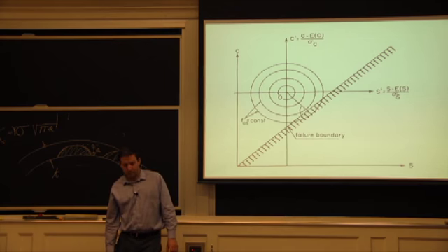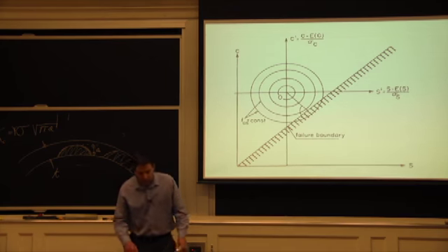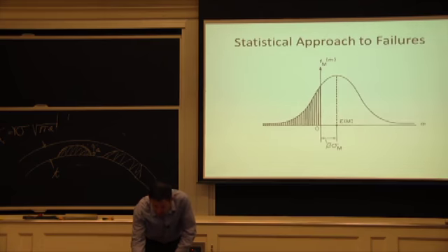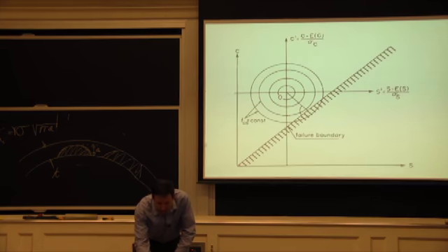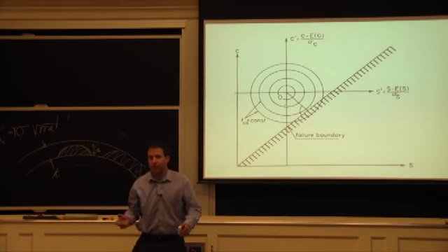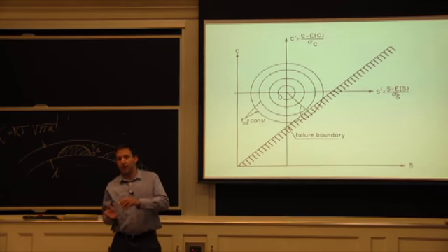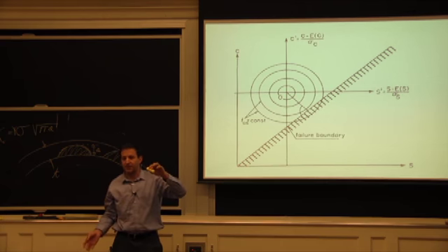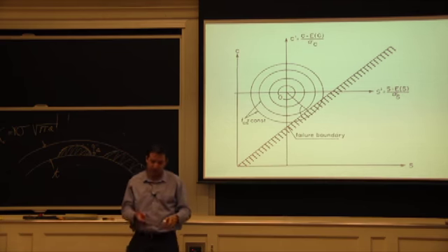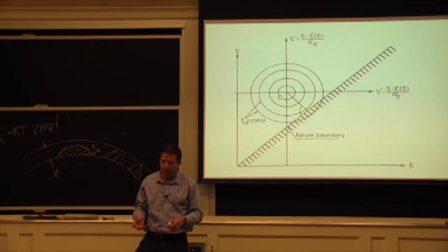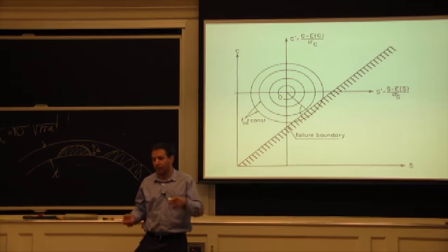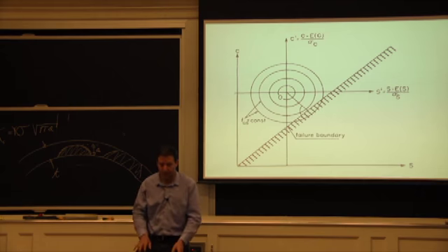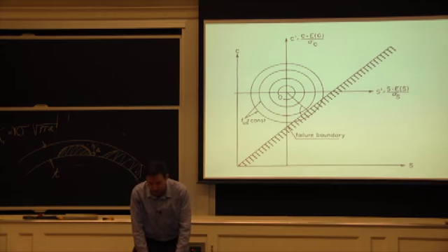They're just saying that this probability of failure is constant around that circle. And that's just assuming that each parameter is working on the positive side and the negative side in the same way. And we have a circle because we're assuming that we have, say, a 20% variation in capacity, and we have a 20% variation in demand. It's not the general case.